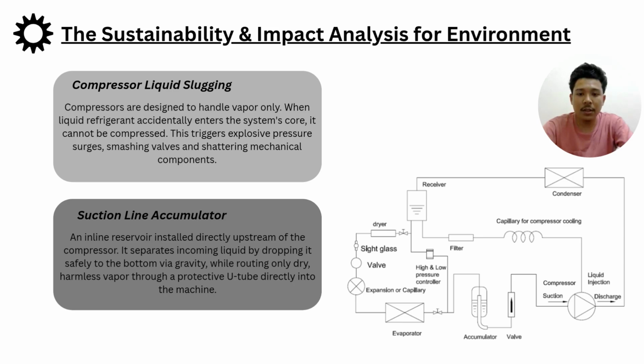Moving into phase 3, let's analyze our environmental impact, specifically regarding compressor liquid slugging. Compressors are designed to compress vapor, not liquid. If liquid refrigerant enters the core, it causes explosive pressure that can shatter valves and ruin mechanical components.